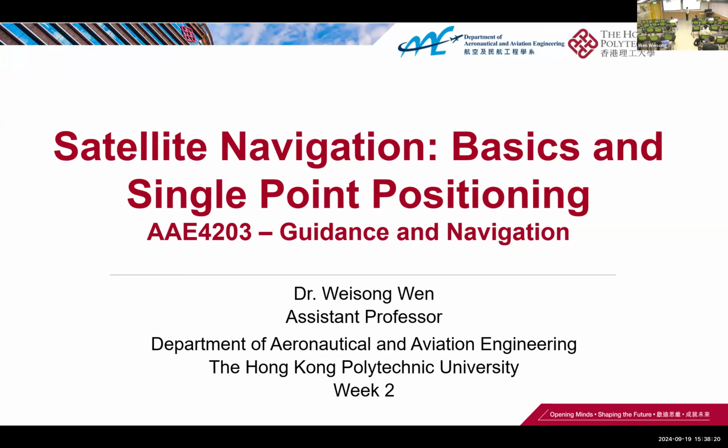Today we are going to talk about GPS positioning with accuracy of 3 to 5 meters. The second level is called differential GPS. It means we have some correction data from a reference station. In Hong Kong, all the correction data are fully available to us. This can lead to sub-meter accuracy, maybe 0.5 meters, in open sky. All these accuracies are based on the assumption that you are in open sky. Level 3 is real-time kinematic, always called RTK, where you can achieve around 5 centimeters accuracy. This is also based on correction data from the reference station, and it also makes use of another measurement called carrier phase. Later we are going to introduce this.